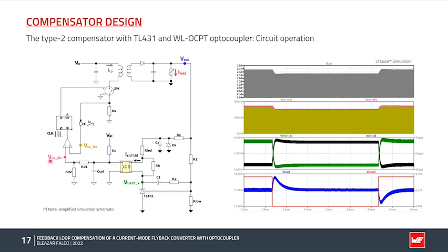and at the input of the comparator, it sets a lower peak current limit in the converter, and we can see how the transformer magnetizing current, the primary current, also reduces, and the output voltage then can go back to its regulated value, because now less energy is being stored and transferred to the secondary side in each switching cycle. Note that the same will happen, but the other way around, if there is a sudden increase in the load current of the converter, as we see here.